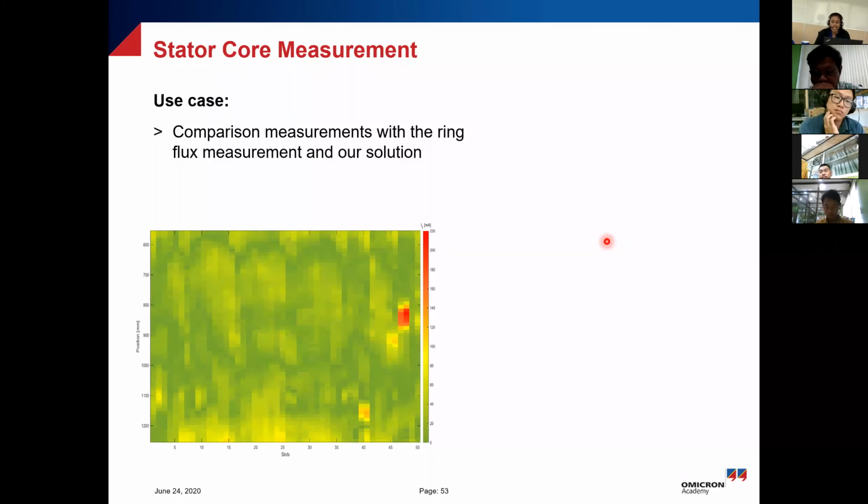So maybe that could have been avoided if we did certain tests on a routine basis. At least as far as I understand, I think we could have avoided that if we did some tests in offline condition on a routine basis. Like we used to do regular tan delta and IR. That's the only test that we used to do. The equipment definitely gave 40 years, but after 40 years it did fail. I believe that's the case. In service I've seen 30, 40 years, at least for old generators. New generators we don't know as of now, but old generators, yes.